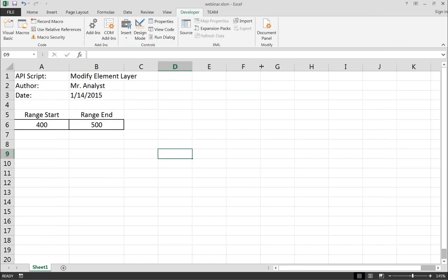To give you a little background on what the type library affords you, it includes a list of the objects, properties, and methods from the FEMAP API. And it makes it easier to program in Excel, as you'll get pop-up tooltips in real time as you program. The tooltips will give you all available properties and methods related to a particular object, or a parameter list for a method that you may be defining. And that's going to make it very easy to program in Excel.